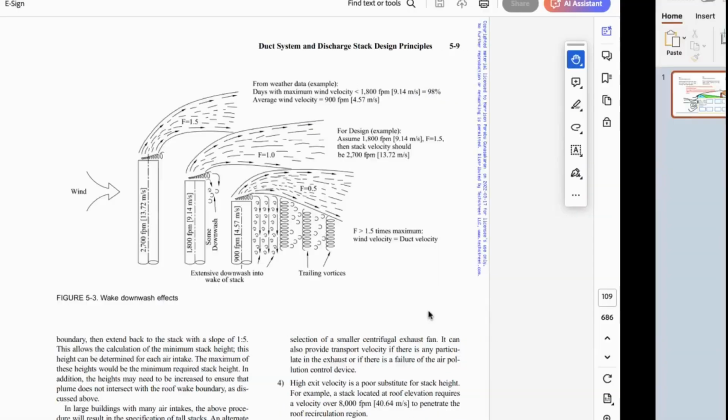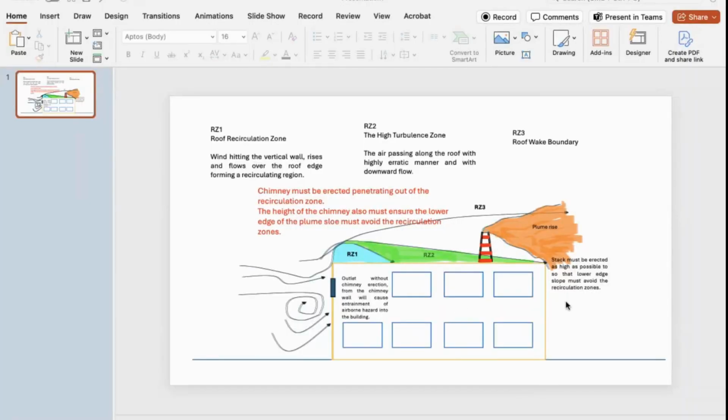The chimney is going to basically splurge the discharge. Assuming we have sulfuric acid with a concentration of 500 ppm here, that 500 ppm is not going to go through dilution, probably a very small amount. By the time it drops about 20 meters from the periphery of the stationary source, it's still going to be about 400 ppm. Let's say we have a dispersion which goes vertically, that 500 may drop to about 100 or even lower. But again, this is just for explanation, as the plume has its own limitation.